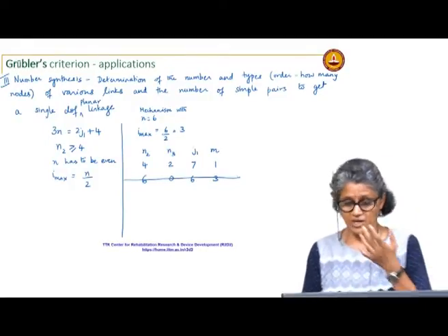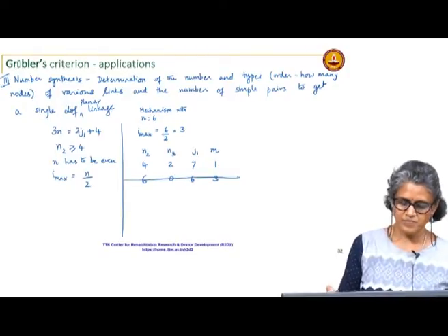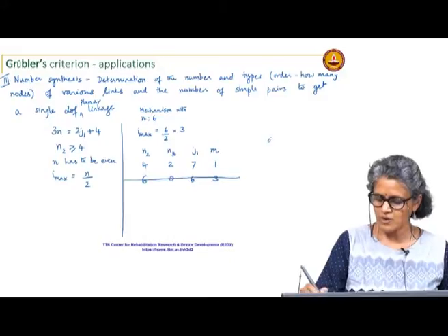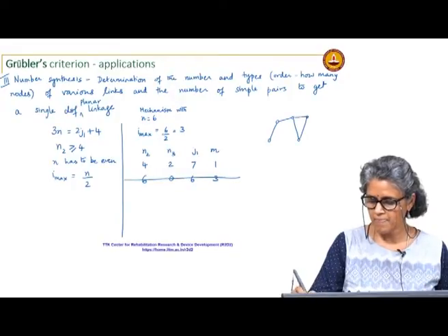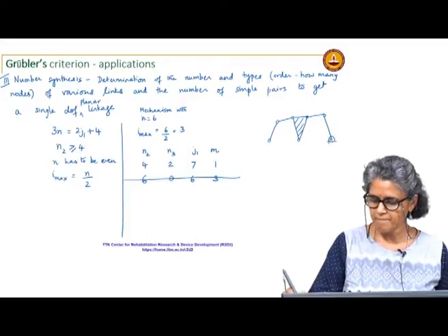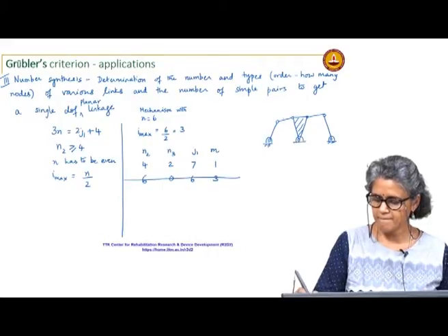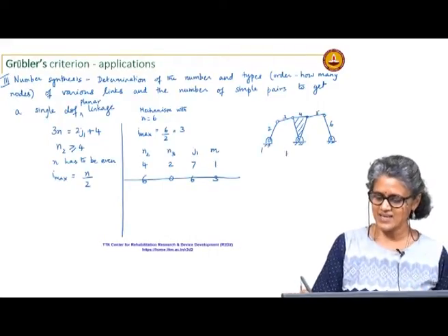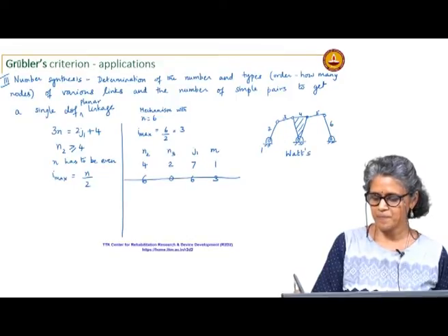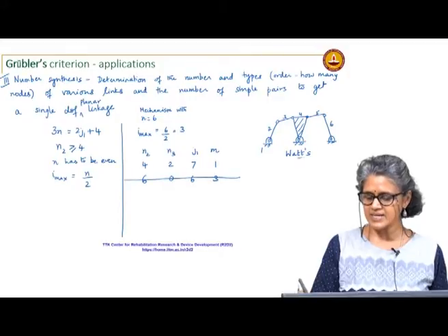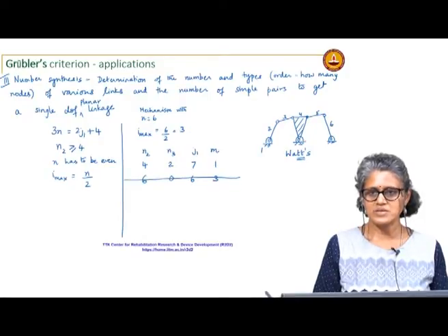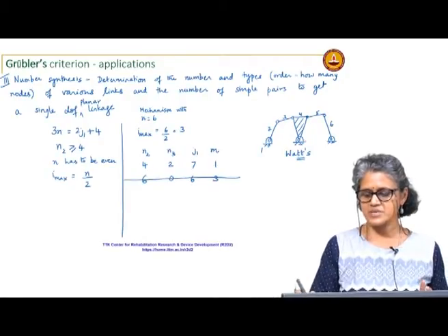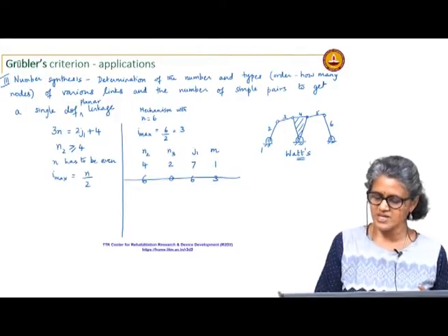Okay. And that is how you get the 2 configurations of the 6 bar, which you have seen before. One is the, do you remember? Anybody? So, you have 2 ternary links. This is the Watts configuration. In the Watts configuration, the 2 ternary links are directly connected to one another. That is one way to remember. Direct connection between the 2 ternary links in the Watts chain.